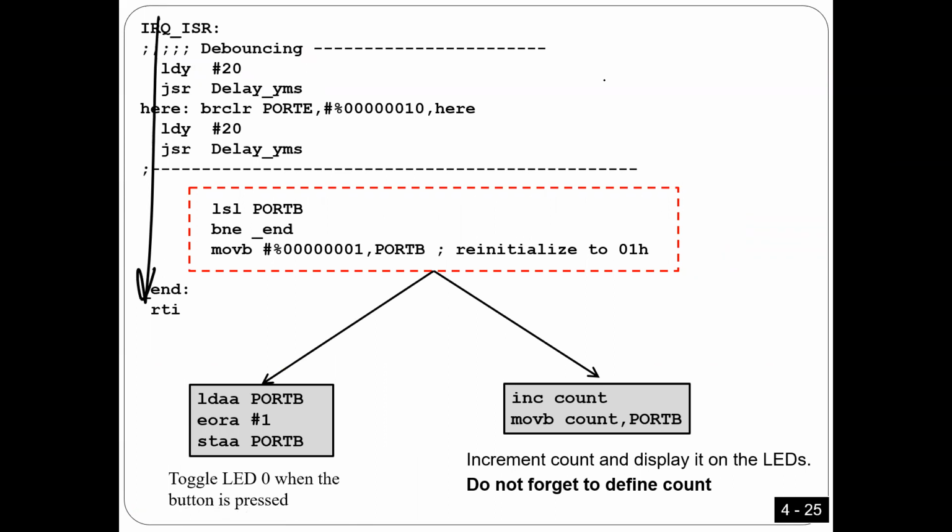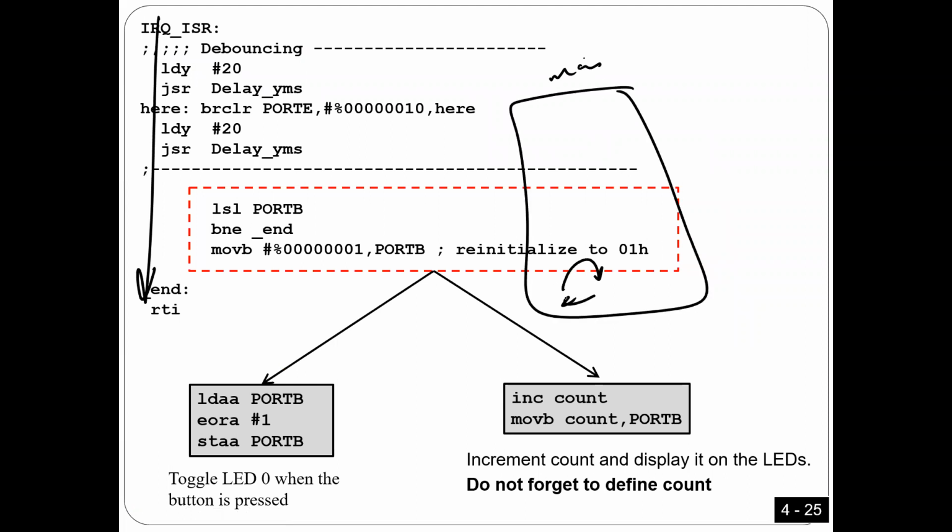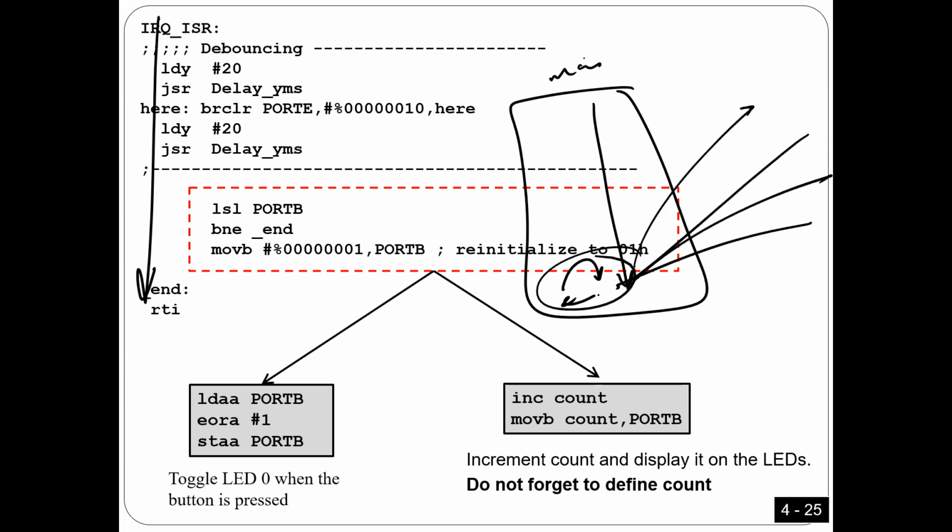So always, guys, for the main program, either I have to loop here, so that once I come here, I'm going to keep looping here, okay? And if there is an interrupt, I'm going to go and come back, okay? But I have to freeze the program here. Otherwise, the program is going to go execute this subroutine, right? Or you are going to go to the beginning again.